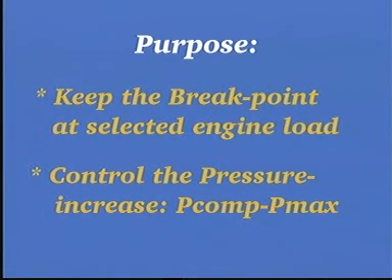The purpose of this adjustment is to keep the break point at the selected engine load and to control the pressure increase. An excessive pressure increase may lead to a poor cylinder condition. In this event, contact the engine builder before making any adjustment.